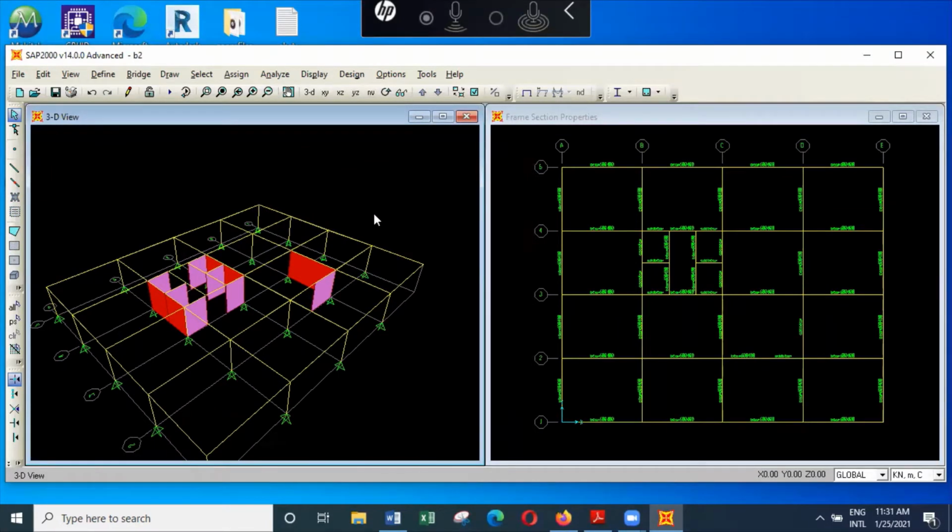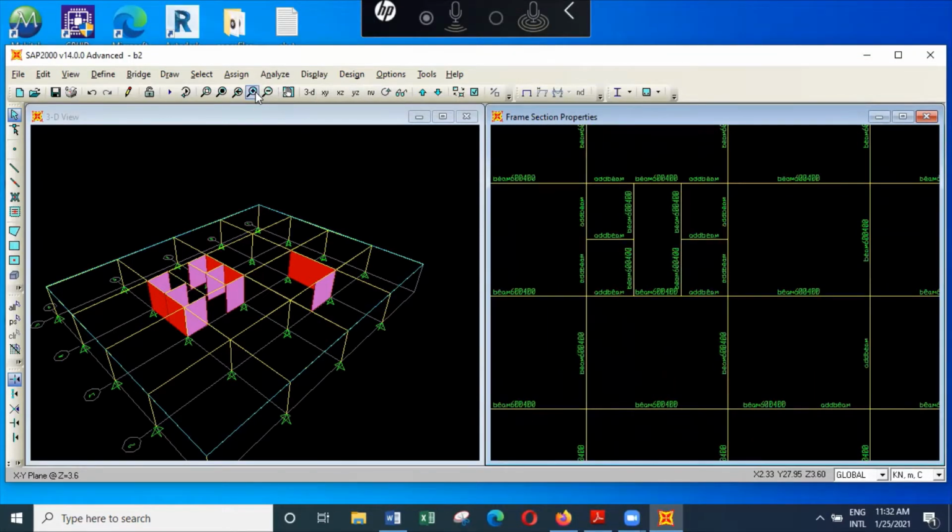Because I'm going to have about 30 floors for this particular building, sometimes the use of 250 millimeter thickness may not be adequate. So I have actually gone for 300 millimeters. And also, if you look at the beam sizes, in a model you can have a few beams that are not actually there in the building. For example, if you consider here, when you have a wall, we don't need a beam. But here I have actually added a beam.